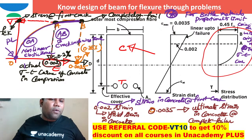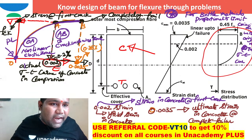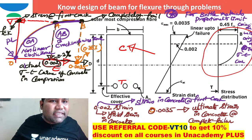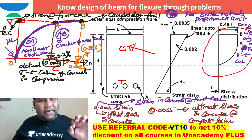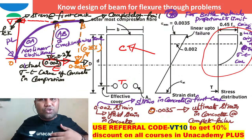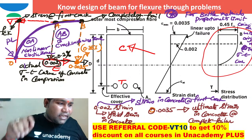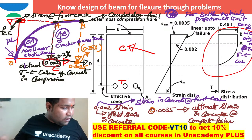So from O to the proportionality limit it would be a straight line, but both have coincided at the origin, so there won't be a straight line portion. After that, the elastic zone continues, but it is a non-linear elastic zone from O to A. That's the reason why, for brittle materials, a straight line stress strain curve is not possible. Only a curved stress strain curve is possible in the elastic zone, which we call the non-linear elastic zone.